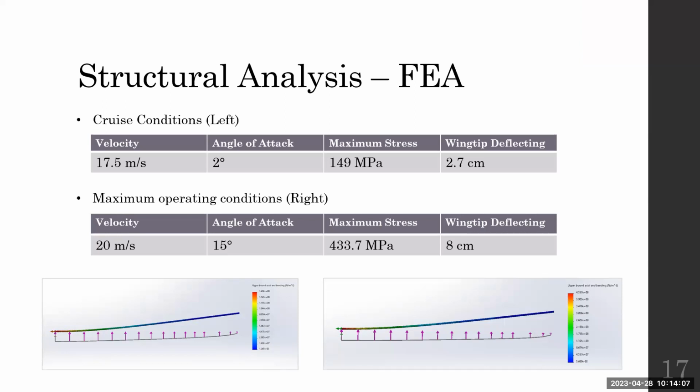Okay, yeah, and you say that 8 centimeters is acceptable, and that's before all the stiffness added. Again, it's fine. So just in the future, maybe do a bit deeper FEA analysis if you're going to include it in a report, because pretty much every design review I've ever had where I had FEA that wasn't super in depth, I ended up getting roasted on it. This is fine though. Okay, thank you.